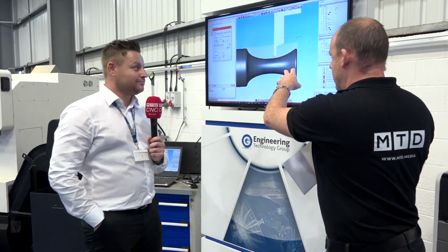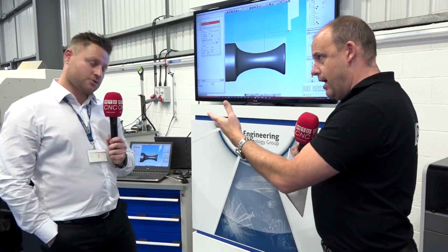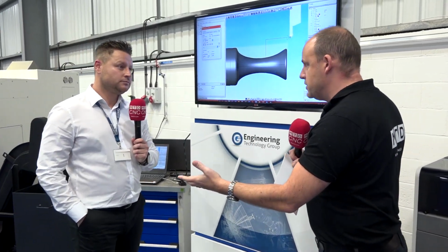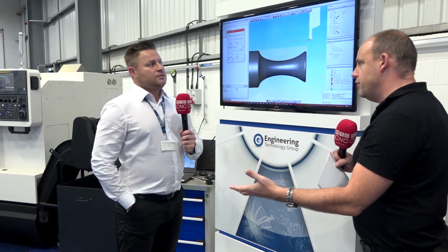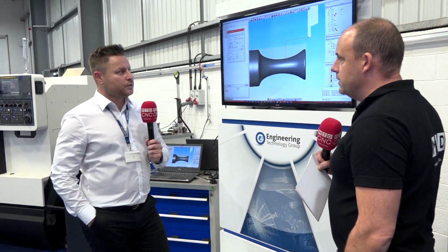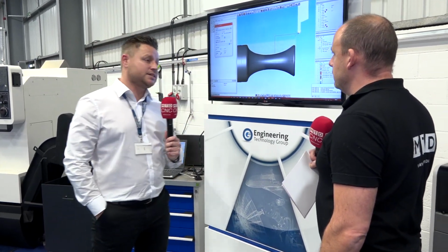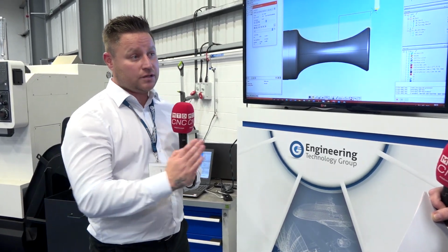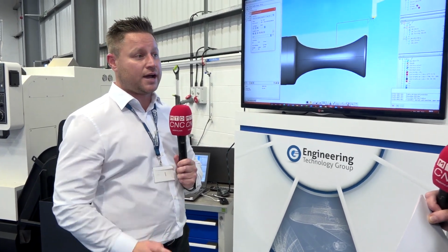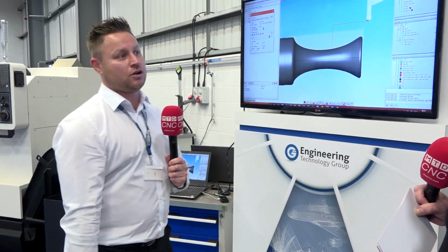Let's finally talk about the actual insert on the tool. This is a Seco tool, is it? Do you favour any specific brand of tool, or can all manufacturers of this sort of insert achieve these results? Nowadays we are using a Seco, but I don't see a limitation on who you're using. It's maybe the type of tool you want to use. Maybe if you can use a solid grooving insert with a full rad, because when you bolt it down, it's more robust, so you can hit it a lot harder.